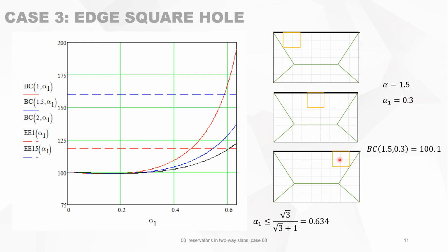So there's no loss of any bearing capacity. This looks strange, but this is because we are not cutting the yield lines, and the influence of cutting the yield lines on top is too small to be significant.